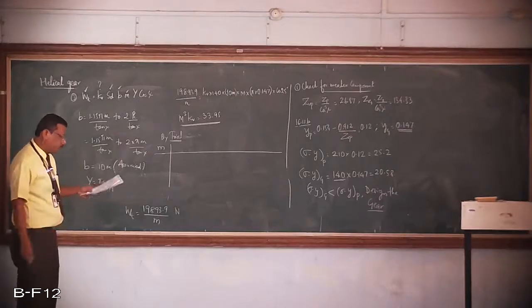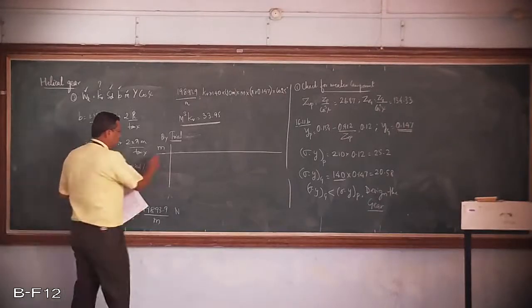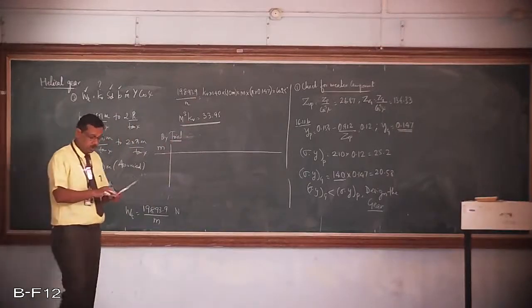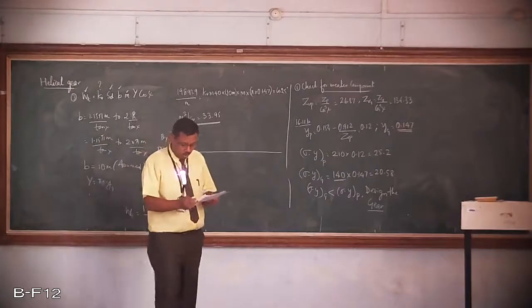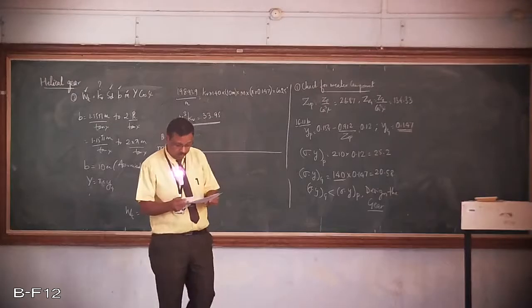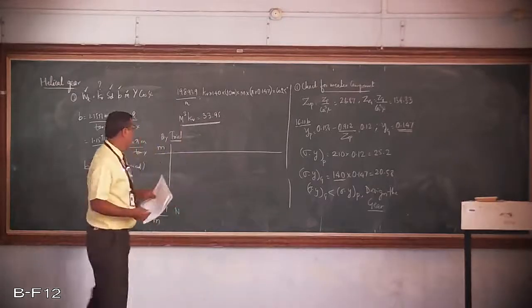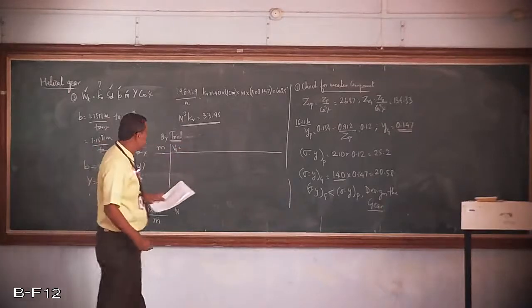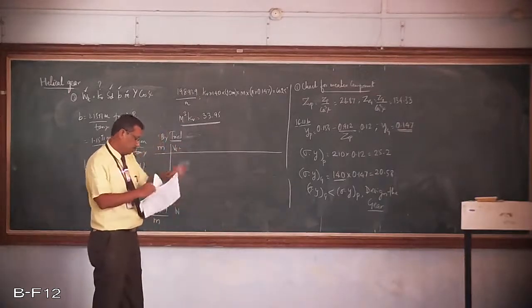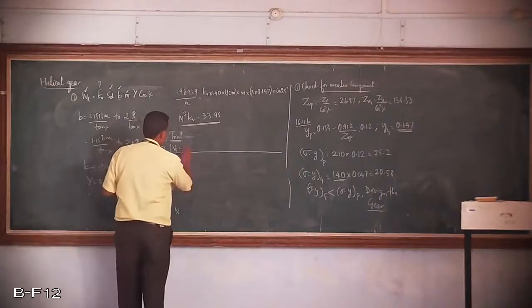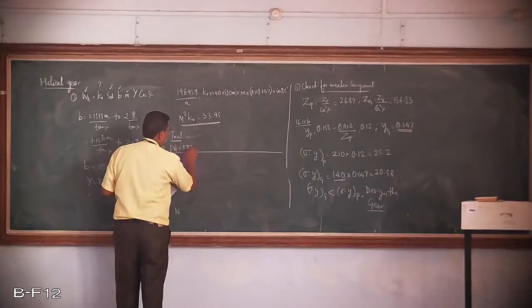Now m is to be selected. Once you know the value of m, for KV we require the velocity. If you see equations 16.32 to 16.35 (16.36 is for non-metallic gears), everywhere we require the velocity of the gear. What is the velocity of the gear? We already found the velocity in terms of the module. Velocity is 0.754 times the module.